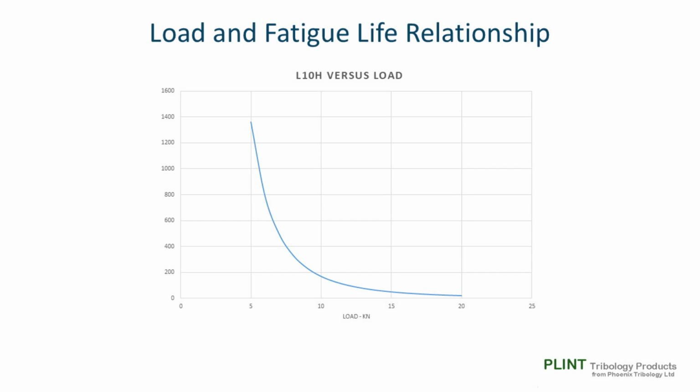Bearing in mind the risk of precipitating other failure mechanisms through applying excessive load, reference to this curve provides some guidance with regard to choosing the optimum test conditions for rolling contact fatigue tests. Not too long and not too short.